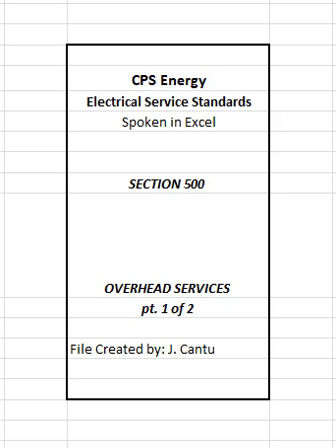506.4 Number of conduits. The number of service raceways permitted to be connected to CPS energy-approved meter sockets and enclosures shall be in accordance with Table 1801 and Figure 1801. Each conduit shall have the same physical characteristics and contain one each of the ungrounded, phase, and neutral conductors. Where 3 conductors per phase are insufficient, a bus service head must be used, refer to Article 509(5). Note: paralleling of service entrance conductors in a single conduit is not permitted.